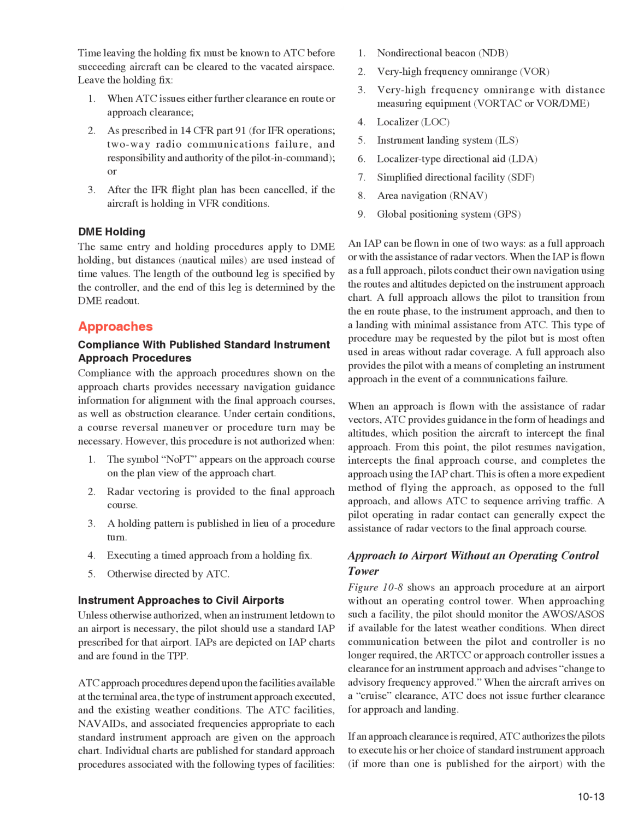for an instrument approach and advises change to advisory frequency approved. When the aircraft arrives on a cruise clearance, ATC does not issue further clearance for approach and landing. If an approach clearance is required, ATC authorizes the pilot to execute his or her choice of standard instrument approach, if more than one is published for the airport, with the